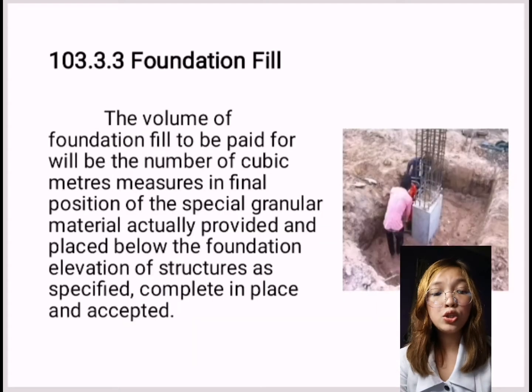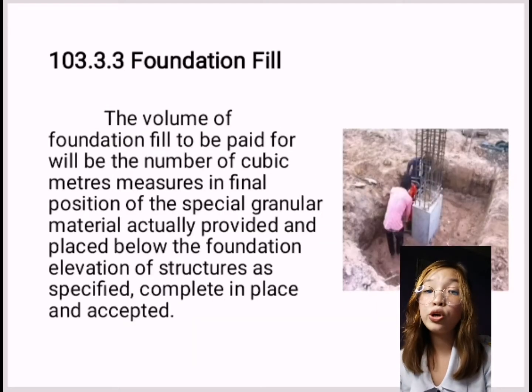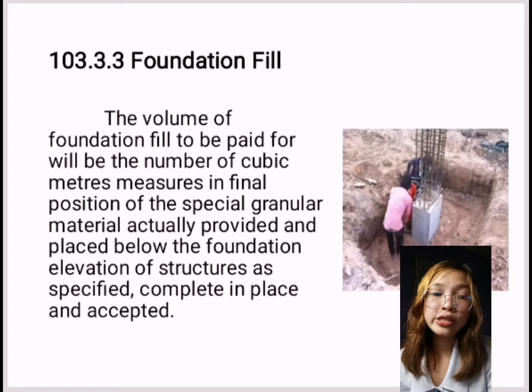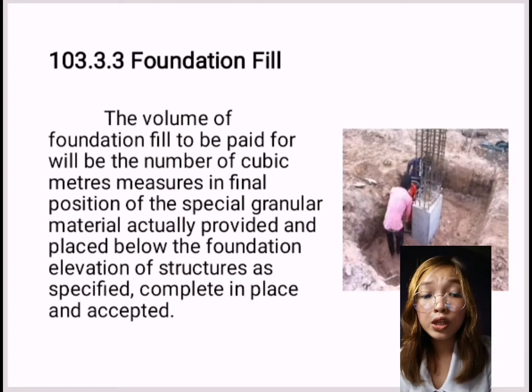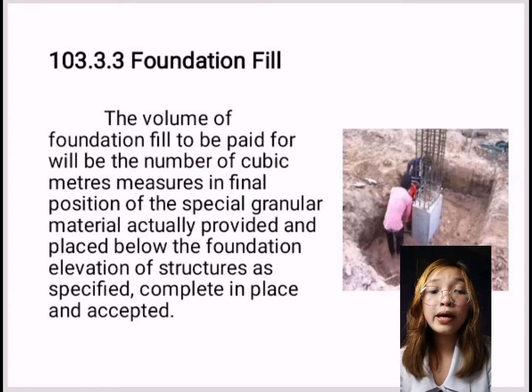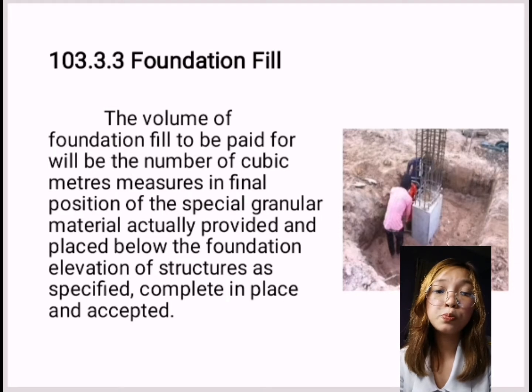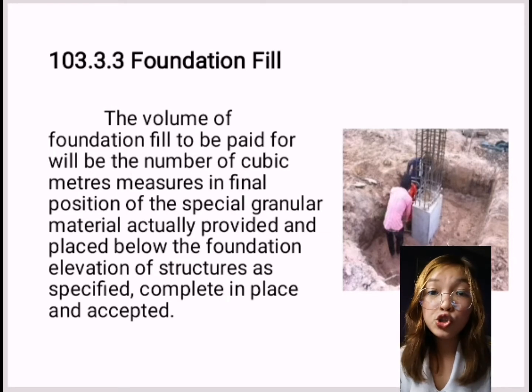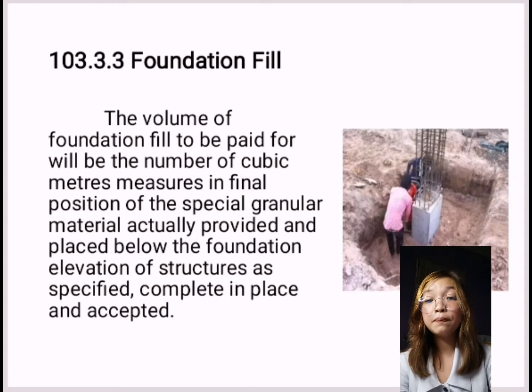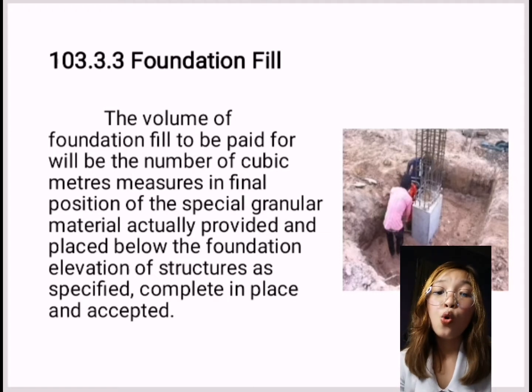So next, let's proceed to item 103.3.3, which is the foundation fill. So, the volume of foundation fill to be paid for will be the number of cubic meters measured in final position of this special granular material actually provided and placed below the foundation elevation of structure as specified, complete, in place, and accepted. Or once initial concrete has been laid, the foundations are filled by directly pouring the concrete.